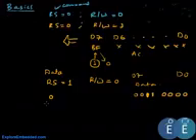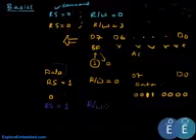So in the last combination, again register select would be 1, wherein it refers to data, and read write would be 1. So what we'd be doing is possibly reading data from the LCD. Now this is not of much help. We do not read data back from the LCD, we only dump data onto it and display it. This could be used in cases where you want to verify the contents of DD-RAM or the CG-RAM.